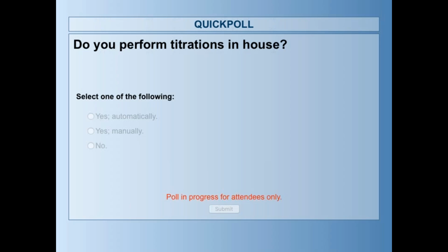Jason Pepper asked, for a BNC connector, do you always need a separate temperature probe? For the most part, Jason, the answer is yes. Some probes will have a temperature probe housed in the same body, but it will have a separate connector on the meter. The BNC connector doesn't facilitate the electronics needed to measure both temperature and pH. You either need a separate pin or a completely separate plug-in for that probe. That's the advantage of DIN connectors, which are a little bit more sophisticated, but also a little bit more exclusive in terms of flexibility between probe and meter.